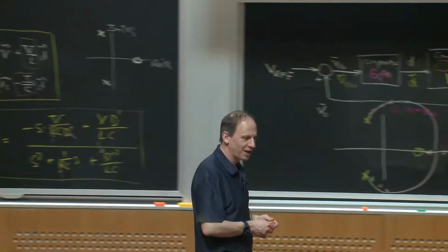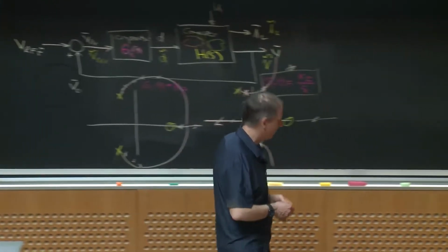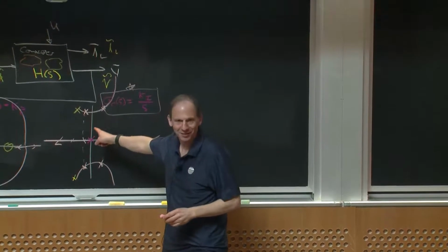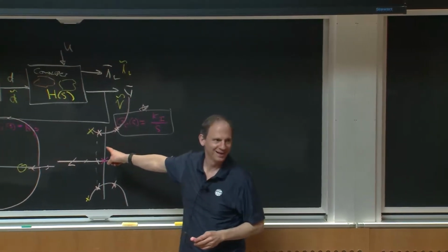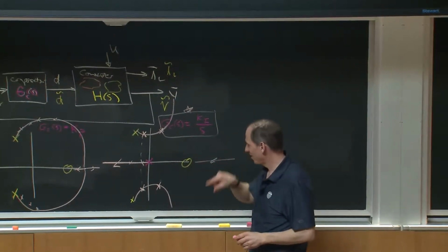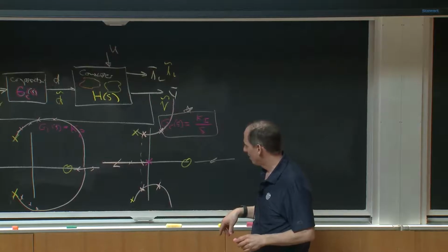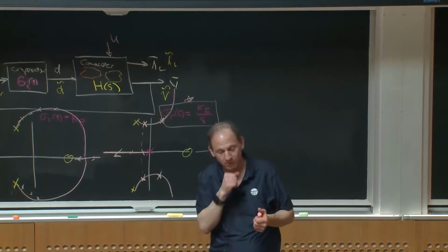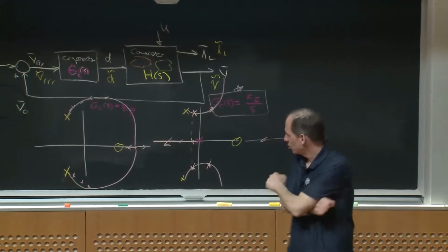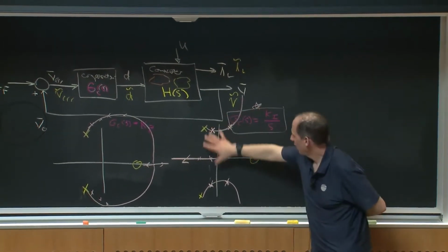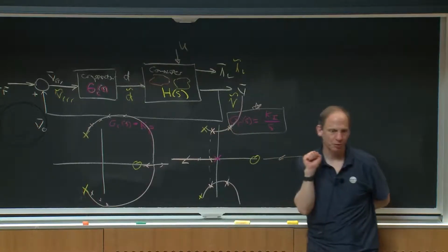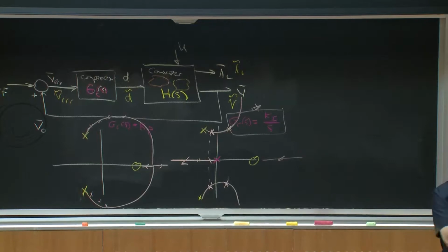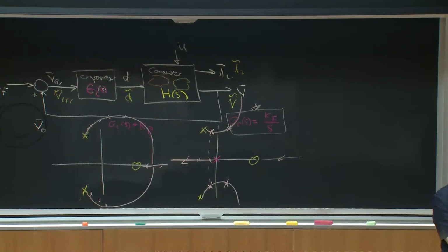You notice the question I dodged is, well, if this is a bad compensator and this is a bad compensator, what's a good compensator? And the answer to that is, there's a lot of things you can do. One of them, if I just wanted to use something like an integral controller, or a more fancy version that's not just an integral controller, but something that was a good duty ratio control scheme.